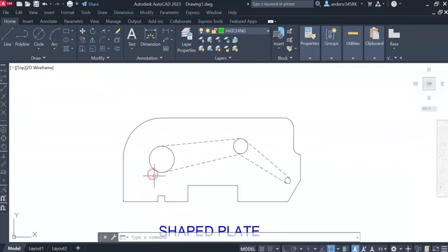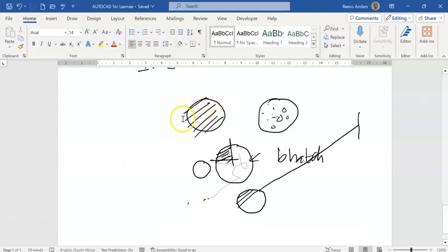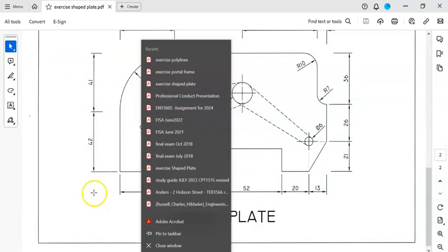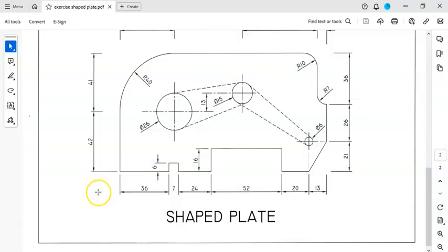Yippee. Can you see there, when you put objects on another layer, you've got more control over what you want to do in future in the drawing. Right, now I'm going to put in my hatch patterns for my circles. It's not on the circles there, but I'm just using that to show you how we are going to hatch a boundary, which happens to be that circle over there.